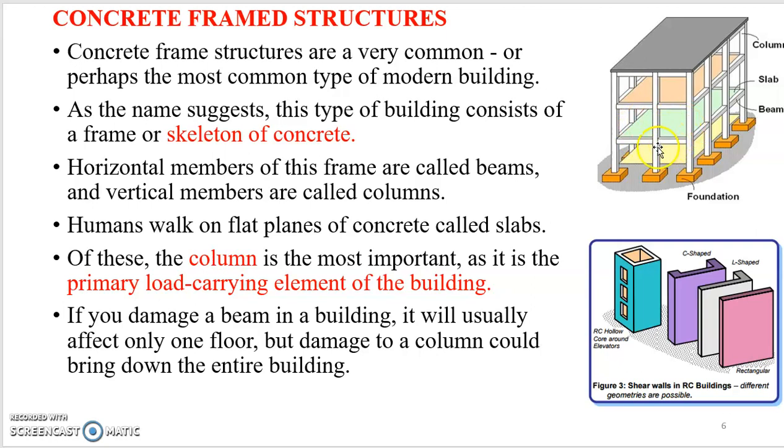Of these, the column is the most important part of the RCC structure, as it is taking the whole load from the above floors and transmitting it to the foundation. So it is said that if you damage a beam in a building, it will usually affect only one floor, but damage to a column could bring the entire building down.